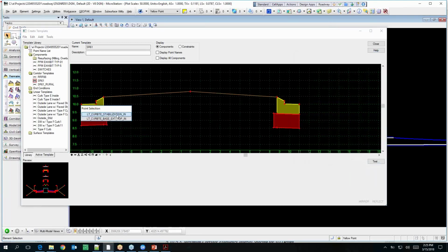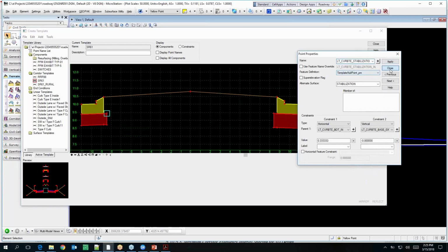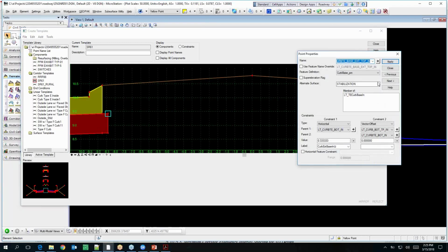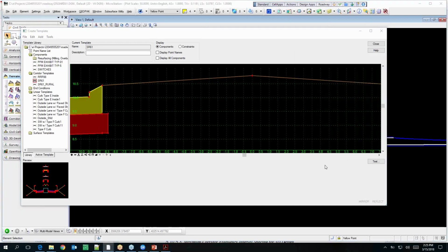Now there's another way that we could test, since we're all just testing now. If you go up to your corridor in the 2D view, one of the corridor design stages is bottom surface, which would be easy enough, except it's not a composite bottom surface. It's only a corridor bottom surface. Right. So that's another option. Which is why I would use the 3D lines. But if all you had was a single corridor, it'd be really easy. We didn't necessarily cover it either.